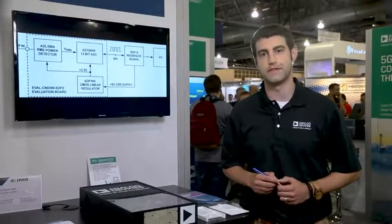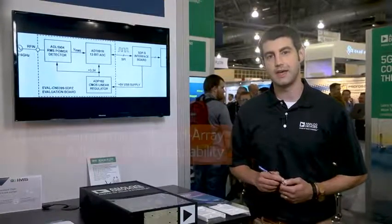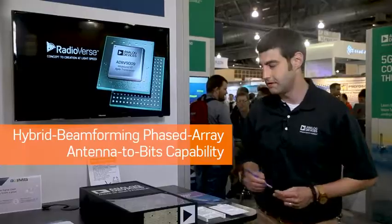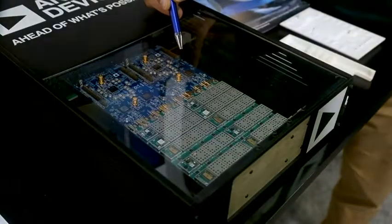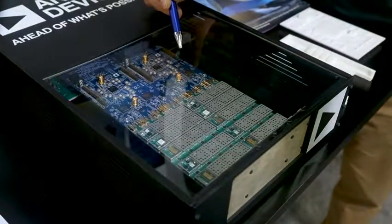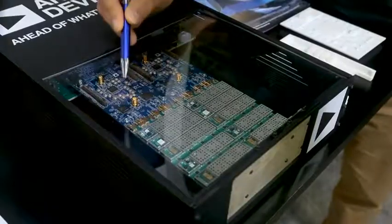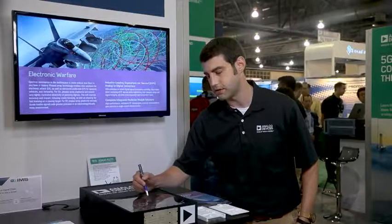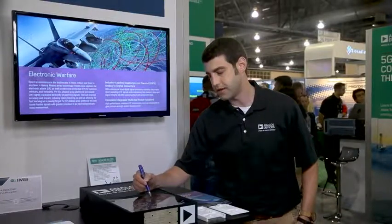Hi, my name is Mike Jones and I'm a Principal Electrical Design Engineer for Analog Devices. Today at IMS 2018 we are demonstrating an X-band phased array prototype, the backbone of which is the ADRV9009 newly released transceiver. This ADRV9009 allows us to have 2 transmitters and 2 receivers per IC. When we combine all 4 of these, we're able to achieve 8 transmitters and 8 receivers, as well as internal LO generation. They also have synchronization features for the RF-PLL phase sync and the JESD phase sync over multiple chip sync.